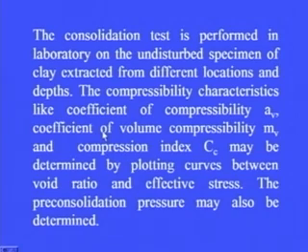The consolidation test is performed in the laboratory on the undisturbed specimen of clay extracted from different locations and depths. The compressibility characteristics like coefficient of compressibility a_v, coefficient of volume compressibility m_v and compression index C_c may be determined by plotting curves between void ratio and effective stress. The pre-consolidation pressure may also be determined.